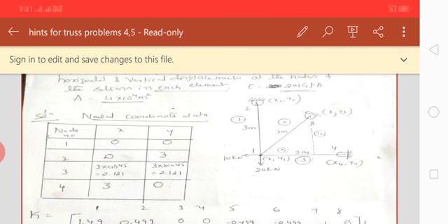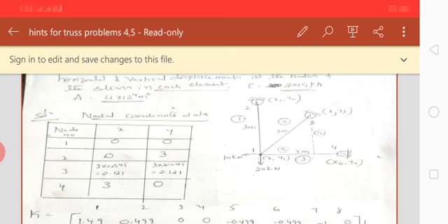There you now have to represent q5, q6, the nodal displacement values at node 3 with respect to x and y, and again f5, f6. There is no f5, f6, so take them as 0, and the nodal values also take as 0. Now you come to node 4. There you have to take q7, q8. That value you have to take as 0 because it is completely constrained, and f7, f8 also you have to take as 0 because there is no force acting on it.